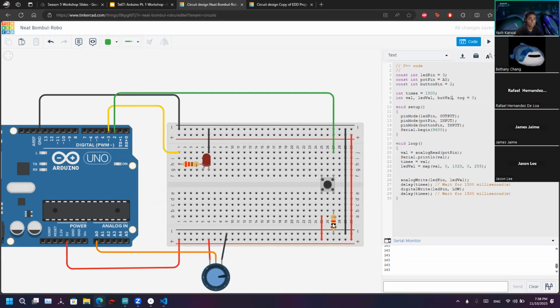Yeah, because certain things also just output a low instead of a high when they're on, or when they detect something. Let's say your garage door laser, right? Its default state is the laser going from left to right, hitting the receiver. When there's a break, it can't receive any data. It'll probably output a low, and then you can use input pull-up and use that to do something with it.